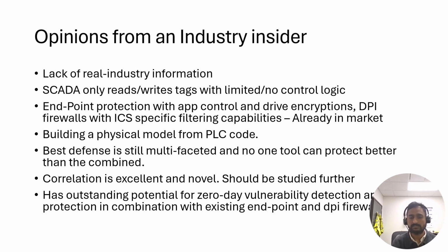That said, Scaphy does remind me of a company that's currently out there. It's called Sepio Security. It's a German company. They actually do this process. They monitor the physical states of hardware, but they do that by adding a secondary channel. Let's say they add a 4 to 20 milliamp splitter to monitor the sensors directly, and they also compare the PLCs, and they build machine learning models to do this overall analysis with correlation.